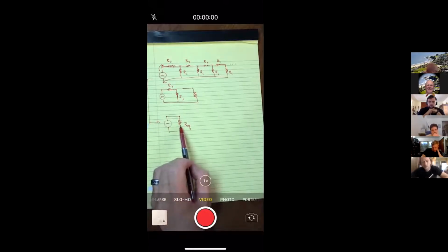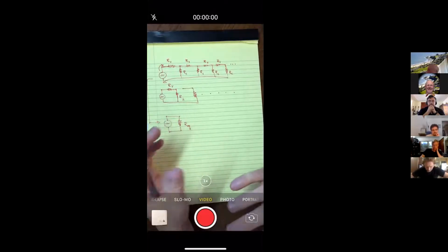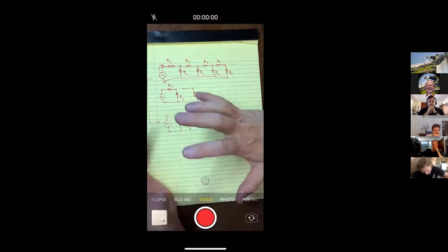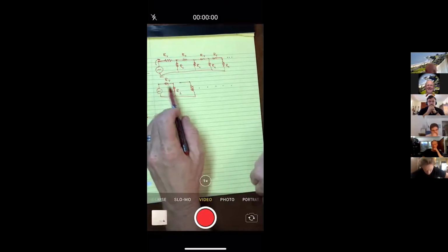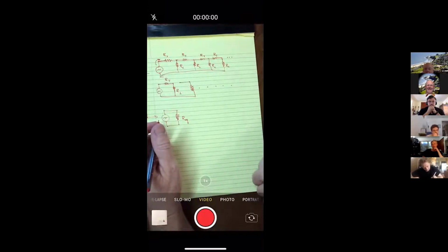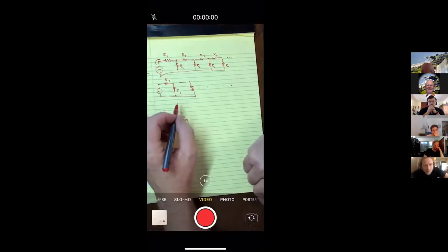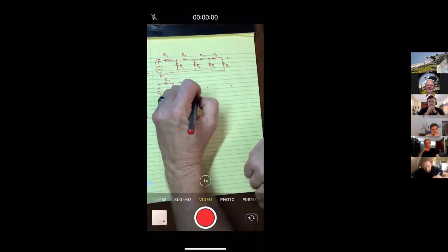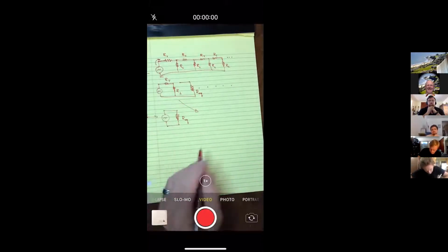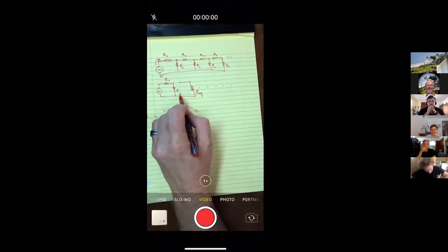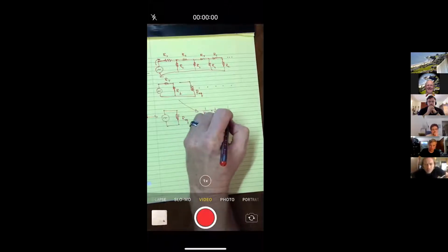Now, if you look at this equivalent resistance, doesn't it look like this going out, but maybe one shy? Right. And so the argument is if you have, and I'll exaggerate, millions of subscribers to your Cox cable, you take away one, and it's pretty much the same thing. 1 out of a million just doesn't change it. So here's a little trick I'm going to play. I'm trying to find what all of them are equivalent to, but I'm going to say the second to infinity is equal to equivalent. And that right here is actually easy to solve because the equivalent and the load would be in parallel. So 1 over the load plus 1 over the equivalent would be 1 over these two.